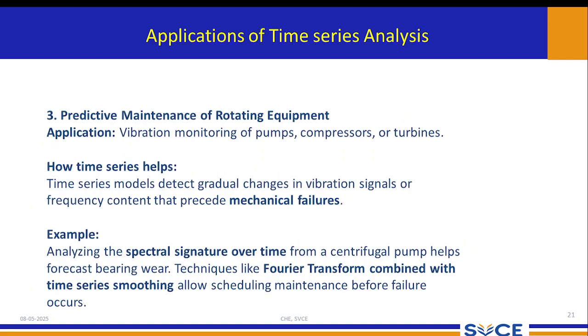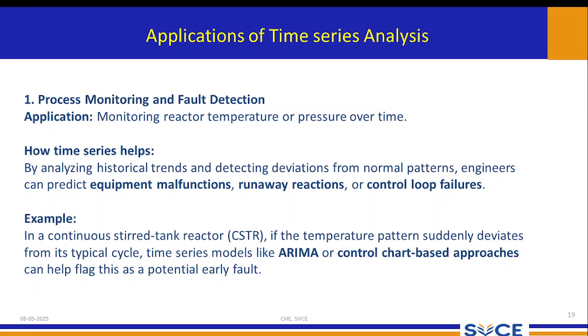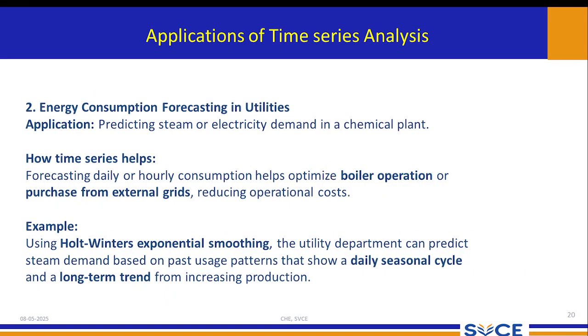Third, predictive maintenance. Let's say vibration monitoring of pumps, compressors and turbines. How does time series help? Time series models detect gradual changes in vibration signals or frequency content that precede mechanical failure. Analyzing the vibration signature over time from a centrifugal pump helps forecast bearing wear. Techniques like Fourier transform combined with time series smoothing allow scheduling maintenance before failure occurs. So this all helps you do predictive maintenance, and optimize the process, energy consumption or process monitoring. That's the example I gave for these three categories.